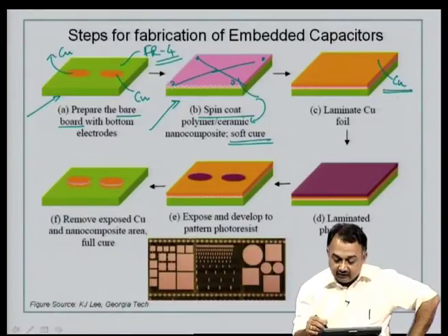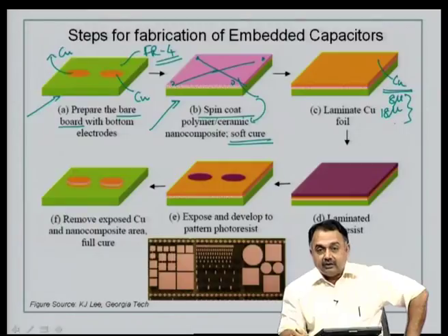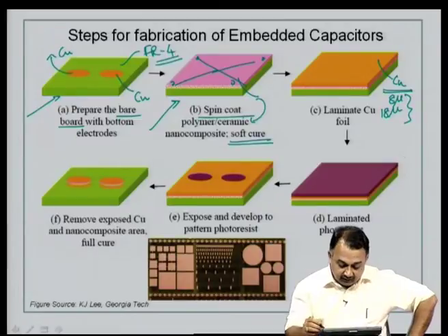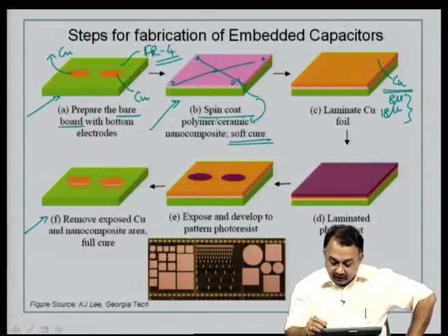The thickness again is determined based on your design. It could be 8 microns or 18 microns depending upon your design requirement, and it also depends on the thickness that you have taken for the bottom plate of copper. Then it is now processed. Okay. Now, you have to realize a design like this that you see in picture F. So, for that you can go ahead with photolithography.